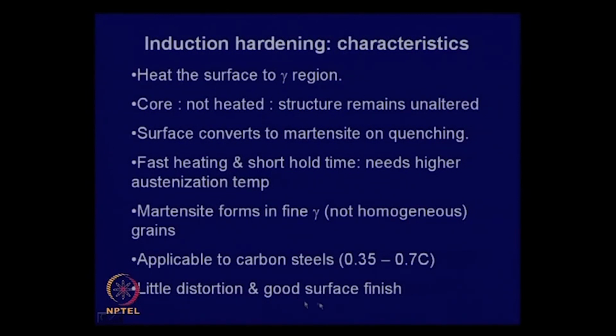Normally when you give a heat treatment, if there is a long soaking period, then the surface gets oxidized and surface finish is disturbed, but here the heating time is very short. So, it retains good surface finish. There is little distortion because the total heat content is also less.